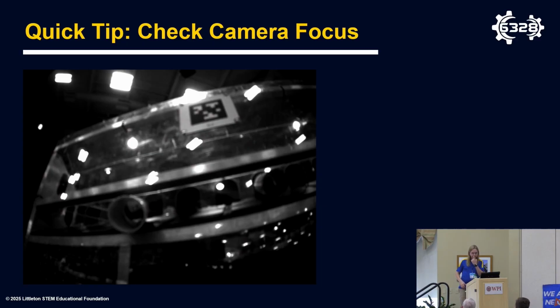Okay, next tip. So this one mostly speaks for itself. Most of your cameras will need to be individually calibrated or focused to an appropriate distance. Here's an example of a match where a camera lens was not properly secured and we drifted out of focus. So even though this April tag is quite close, we can't see it at all. So that's a big problem. It's really important to focus your cameras ahead of time and secure them in place however the manufacturer recommends.